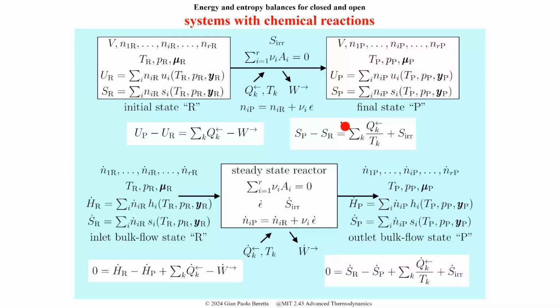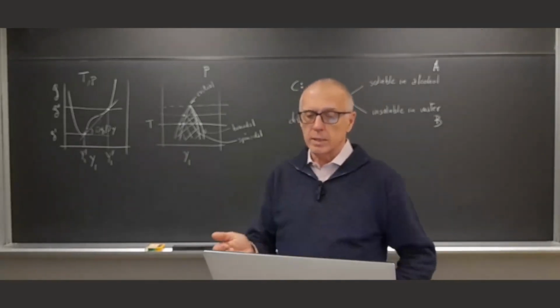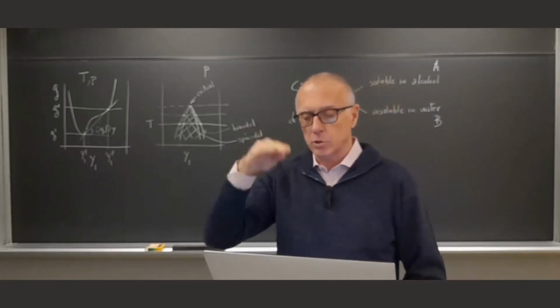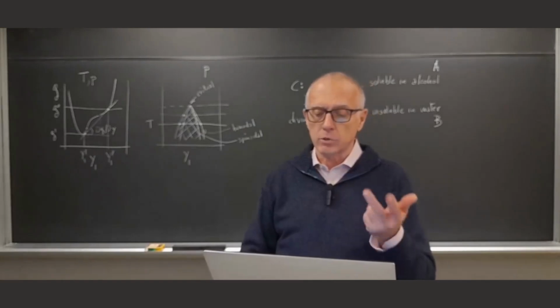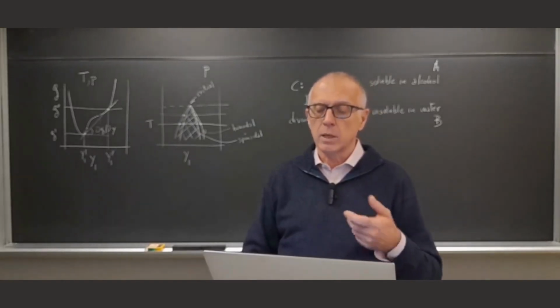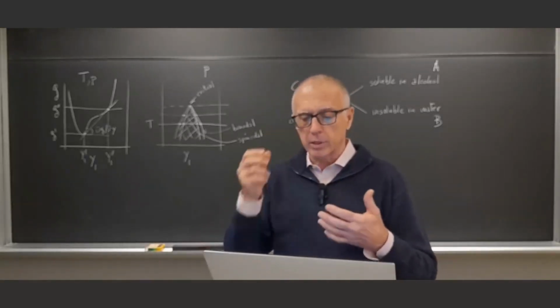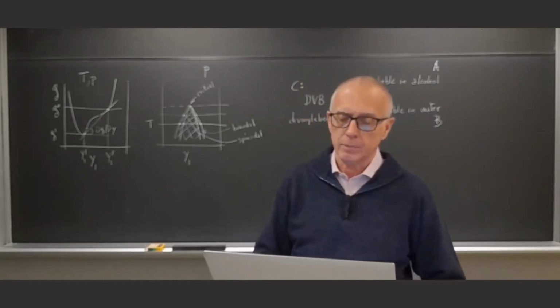You can use the energy and the entropy balance, and perhaps also the volume balance, if you assume that the volume remains constant or relatively constant, because the reaction at the top dead center occurs very quickly, and so the piston doesn't move a lot. Then you have three equations, energy, entropy, and volume balance, with which you can solve for three unknowns. So the various possible problems that can be solved are variations of this.